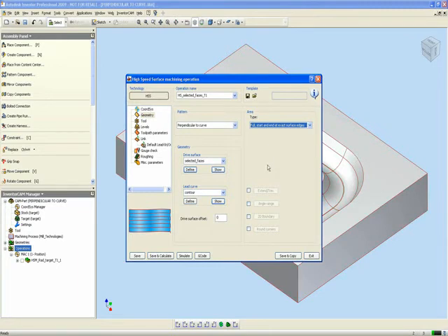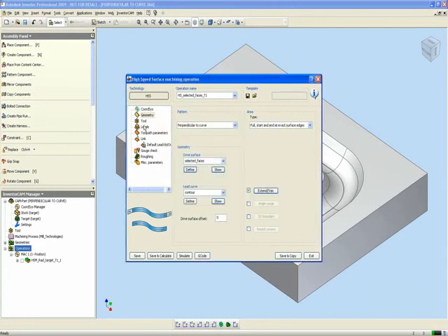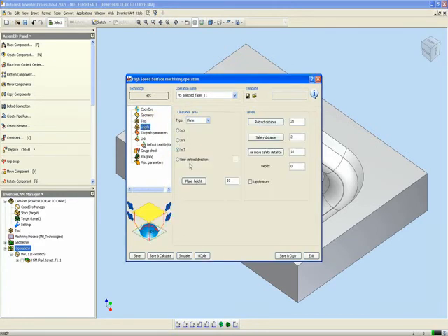So we have the option here of extend trim. By extend trim, as shown in the picture here, I can extend my surface so that it goes a little past my surface, or if I do a negative value, I can subtract from the edge of the surface. I'll simply say extend trim, and I can add a value, or a percentage of the tool, and say I'll add a value at the start of 3mm, and at the end I'll also add another 3mm. In my levels, I'll leave it exactly the way it is.